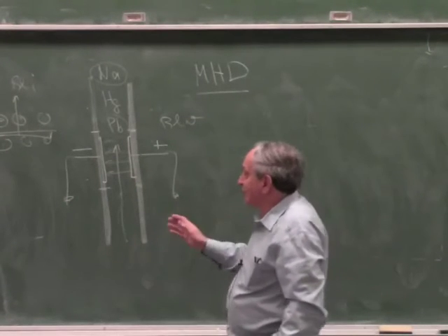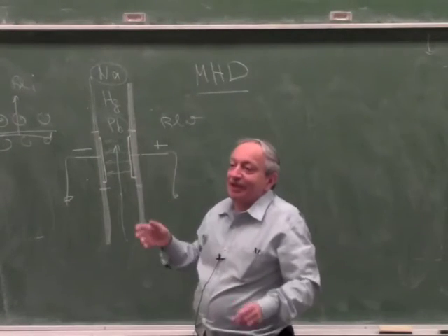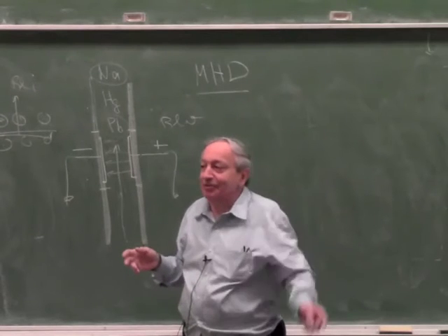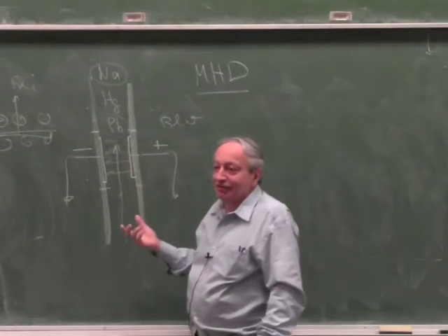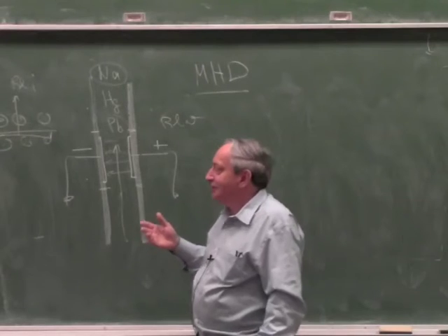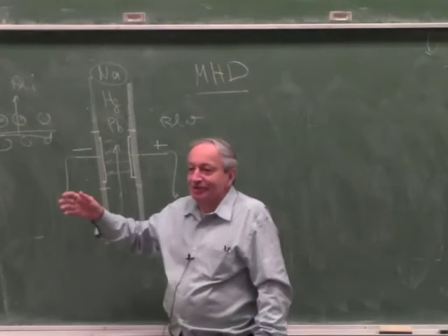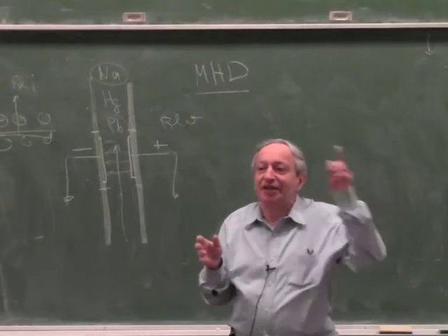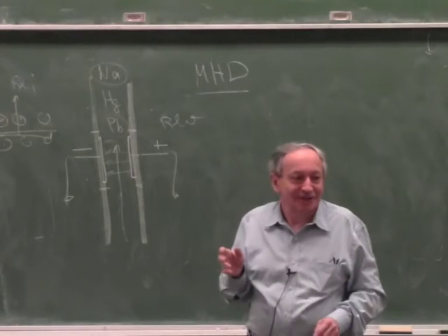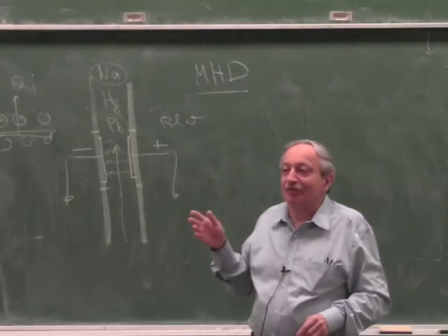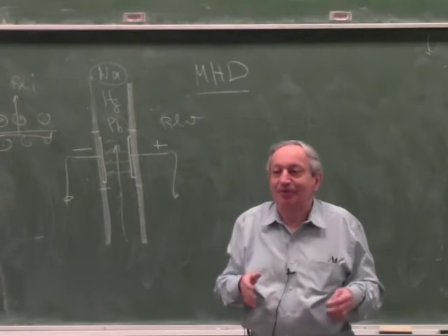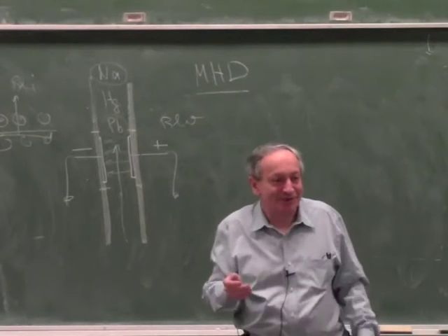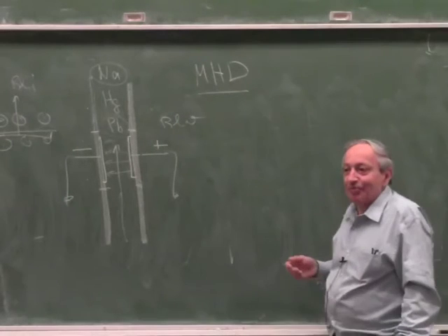If you can run this lead, say by gradients or by any other method, you can make electricity straight from it. So it turns out it's more efficient as a pump. To make it a generator, the efficiency is not good enough because you can't make the molten lead flow fast enough, right? And if you want to make it flow fast, you need a pump, and then the pump needs energy, so you defeat the purpose. But you can make a pump like that.